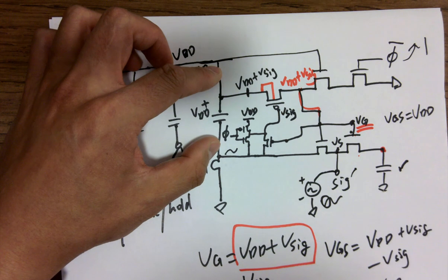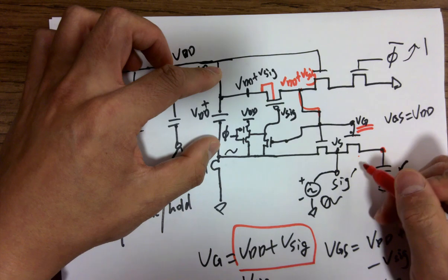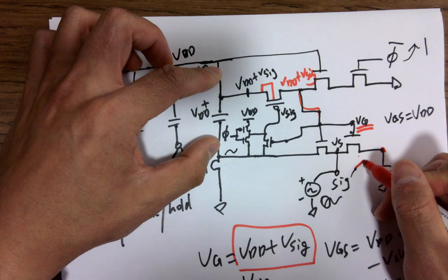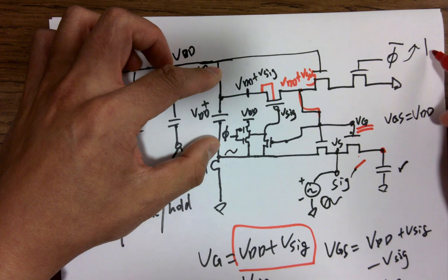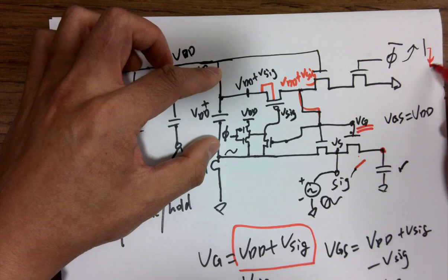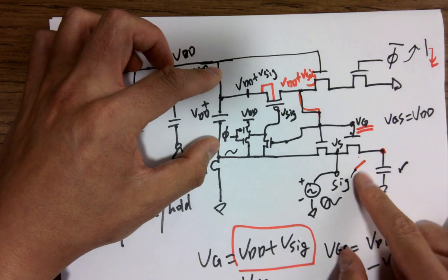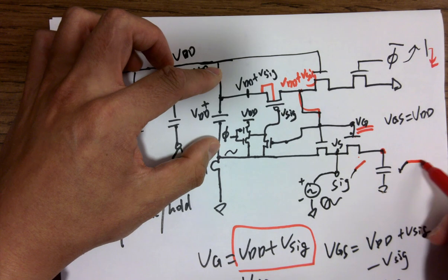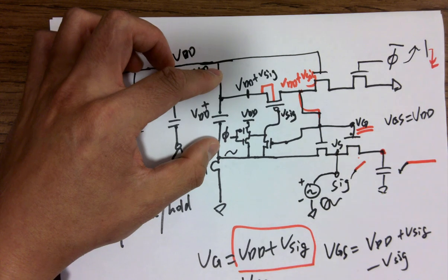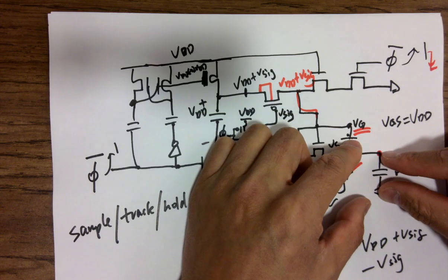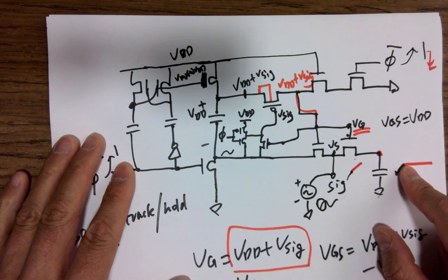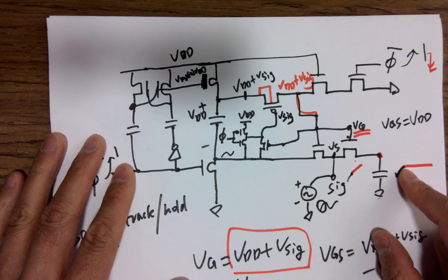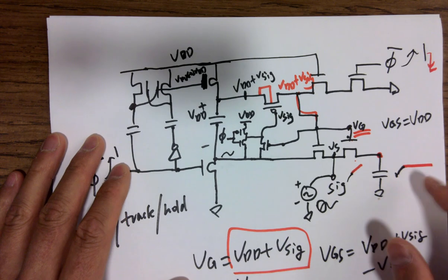And after that, the analog input is not getting controlled; it keeps going up. But at that moment, there's a falling edge, right? What's going to happen after that point? Here, hold. Because this is off, this will be hold. It's going to become the held charge, so whatever the voltage is right before that point is going to be held over there.